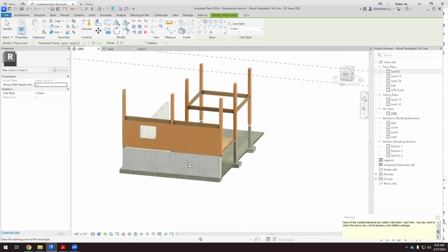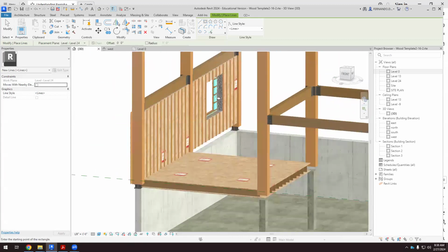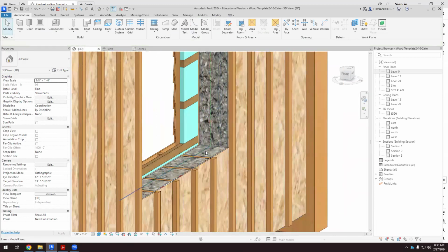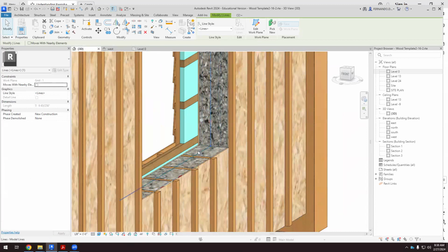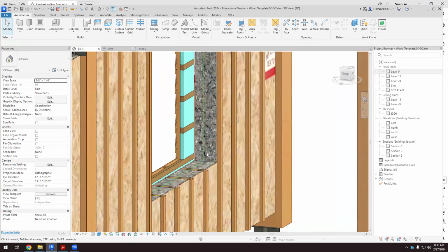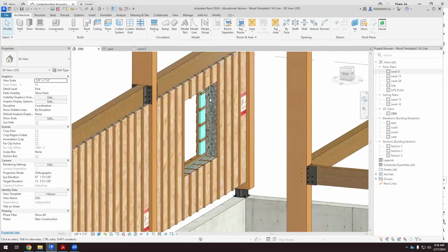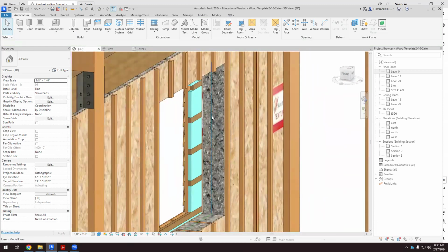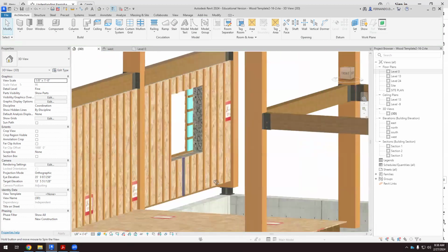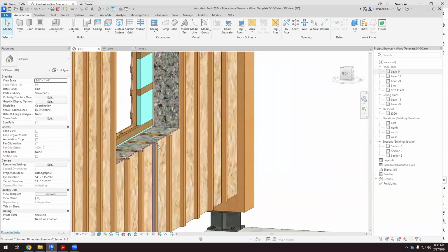And if everything goes well, you see that I have a green line here. This is grid line number 1. And I created this green line. This is the reference, okay? So I'm good, because basically I want to work in this frame, in this opening.